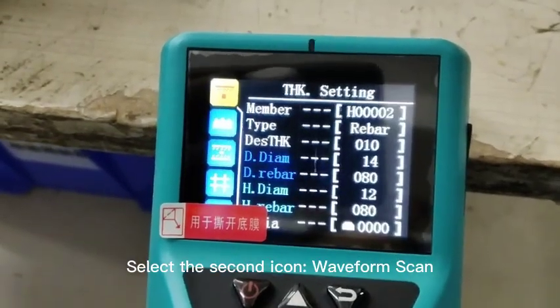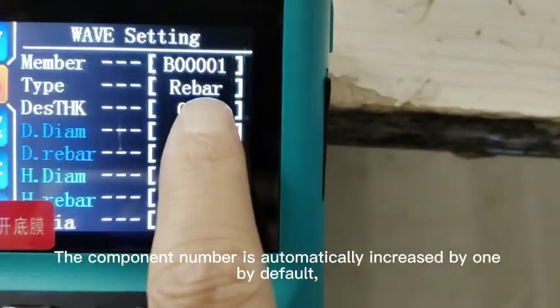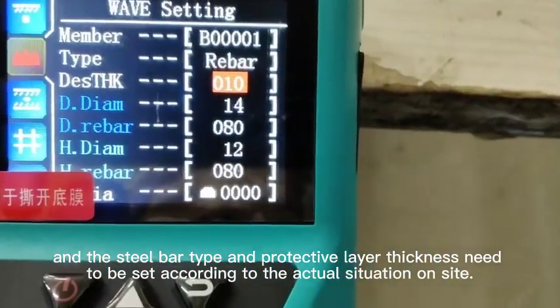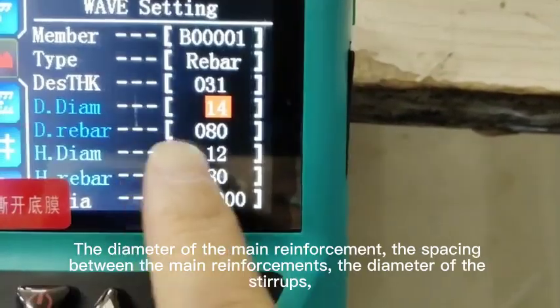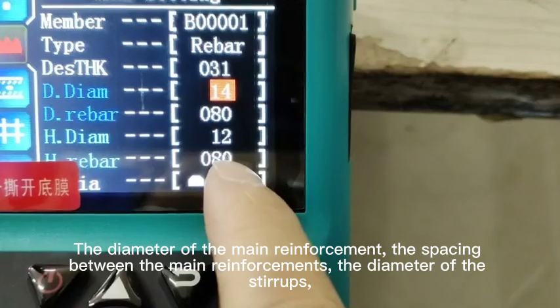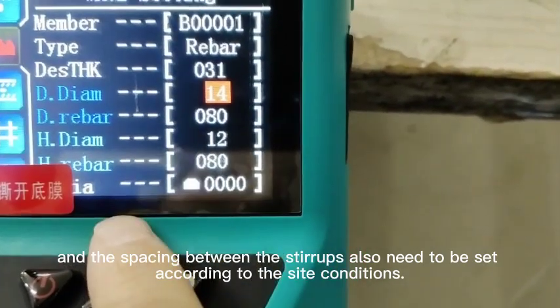Select the second icon, Waveform Scan. The component number is automatically increased by 1 by default, and the steel bar type and protective layer thickness need to be set according to the actual situation on site. The diameter of the main reinforcement, the spacing between the main reinforcements, the diameter of the stirrups, and the spacing between the stirrups also need to be set according to the site conditions.